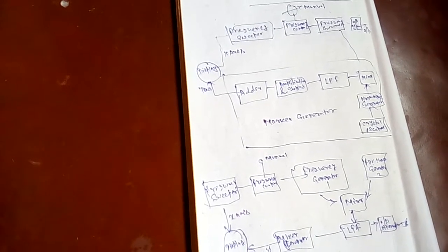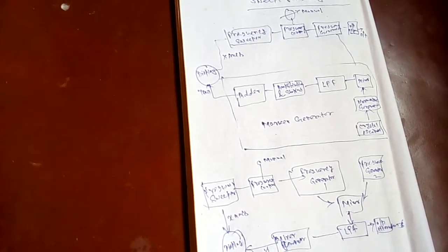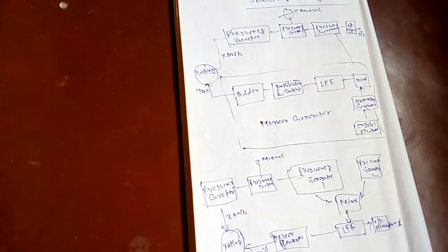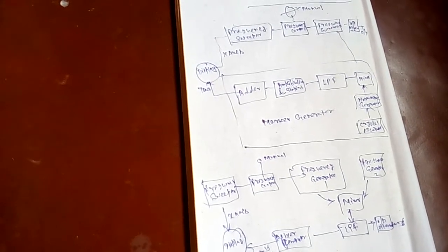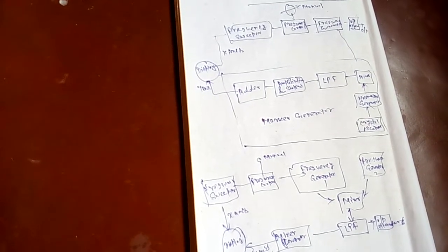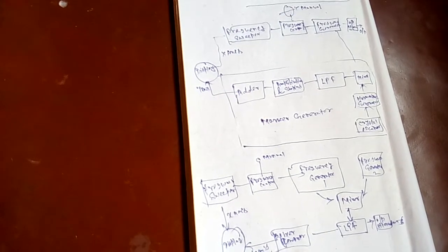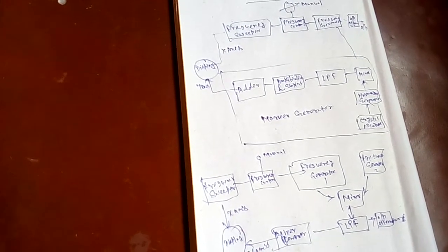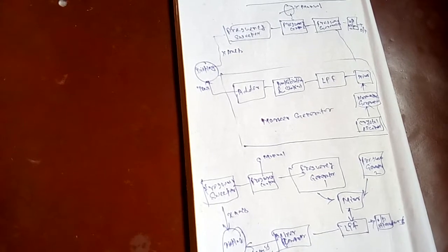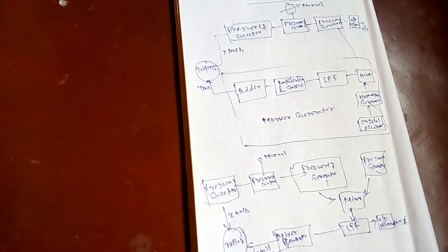However, the non-linear mixer will produce many other frequencies in addition to the required one. Output level control is used with the frequency generator to keep the output amplitude at the set dial value. Usually a radio frequency detector monitors the RF amplitude of the output.